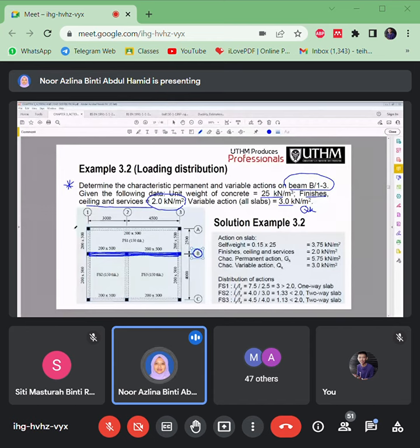Okay, kalau I buat sketch, if I cut here, you look from here, mata letak kat sini, tengok dari sini. So there will be a beam here, and then this is the slabs, right? The slabs, and then this is the beam, this is the slabs, this is the beam. So this will be the beam that you will design. This is a T beam, which is a flange beam.